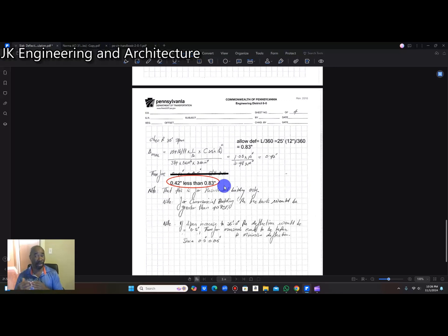If it's going to be a commercial or an industrial building where the loads are much greater, you will have to do the calculation, and I'm sure at that instant it is going to need a flat beam or a downstand beam, a designed beam to withstand the load. For a residential home, which is going to be subject to a load of 40 pounds per square foot or 50 pounds per square foot, when you work that deflection out, you're going to get good numbers, and that slab is going to be safe. But I said, still put the sleeper slab.